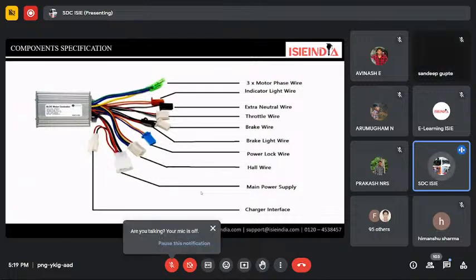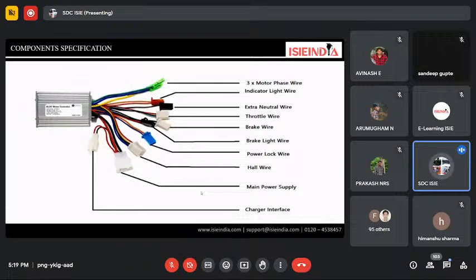Along with that, we have a throttle wire. To accelerate the speed, we connect the throttle. Brake wire, where we step on the brake, along with the power lock wire, Hall effect sensor wire, and main power supply wire. Along with the main power supply, they also have a charging interface. They are giving a power supply to the battery, and to charge the battery they have a charging interface.